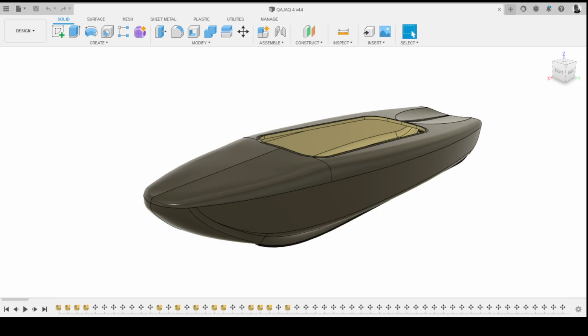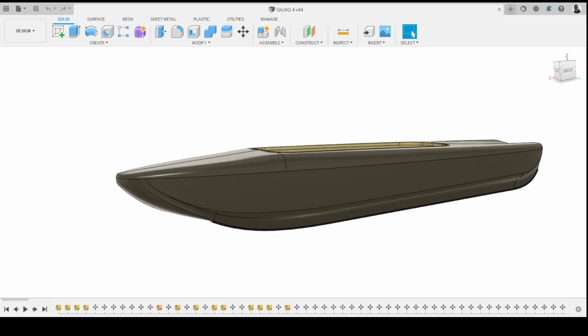Yeah. Any other ideas why I might have chosen surface modelling to create this shape? And this you wouldn't necessarily know without seeing it, but how it's made. Variable thicknesses of the material, in fact. Well, yeah, although the other flip side of that, all the material was about 4 millimeters thick throughout the whole thing. It was one thickness. There weren't variable thicknesses at all. There was no internal structures at all. It was just that external shape which had been moulded in 2 halves, and it was split along this split line along here. So that was one moulding up here, and that was the other moulding down there, about 4 mil thick.